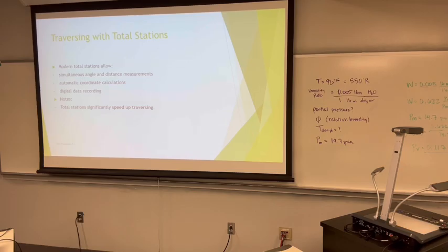If you have multiple people, it goes a lot smoother, a lot easier, a lot quicker. We'll work in multiple groups and we'll have somebody run a backside, somebody run a foresight, somebody run the instrument, recording the angles, and we'll rotate around as we go around the polygon.